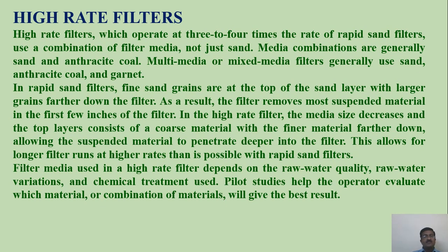High rate filters. High rate filters, which operate at 3 to 4 times the rate of rapid sand filters, use a combination of filter media, not just sand. Media combinations are generally sand and anthracite coal. Multimedia or mixed media filters generally use sand, anthracite coal and garnet.